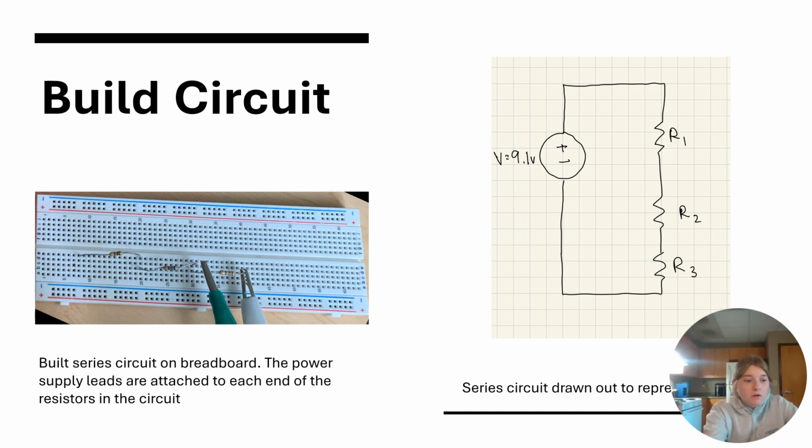of the breadboard, the circuit is not complete because the power supply probes are not connected to the resistor R1 on the left and R3 on the right. The resistors should not touch, but must be connected through the breadboard.